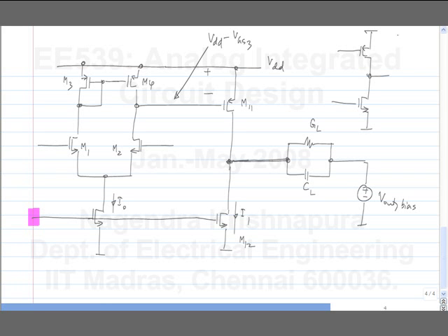So you will have structures like this in the amplifier. For instance, here also, M2 is a current source, M4 is another current source, and they are connected together. If you try to make this in open loop, it will not work. But once you put it in closed loop, it will get the correct value of bias.